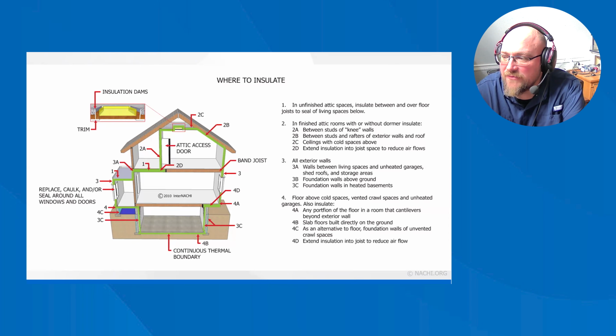Adding insulation may require hiring a professional contractor. If the house is old, the electrical system should be checked by an electrician if the wiring is degraded, overloaded, or uses knob and tube wiring. It is hazardous to add insulation when conditions such as these exist. Adding thermal insulation within a closed cavity around wires could cause the wires to overheat. Code does not allow the installation of loose fill, rolled, or foam in place insulation around knob and tube wiring.